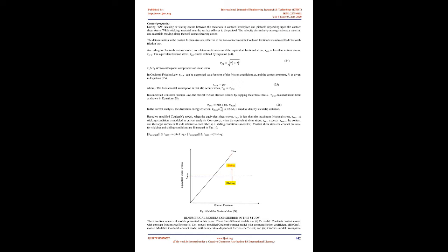In the model, the initial temperature is set to 25 degrees Celsius. The heat exchange between the top surface of the workpiece and the shoulder involves consideration of convective heat transfers. The initial temperature boundary can be expressed as shown in equation 18. Where the first symbol is the specific mass heat capacity, the next is the material density, the next is the thermal conductivity, then the heat conductivity in each direction, the heat generation rate, and the absolute temperature. The energy balance equation 19 can be expressed as equation 20.